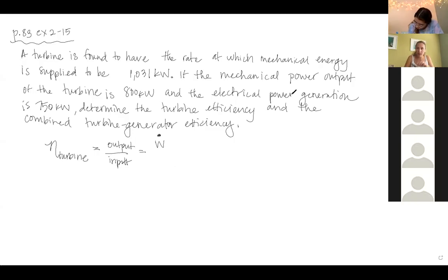So the turbine has that power happening over our moment arm, applying some torque and turning that generator. So there's some shaft work being done, and it's going out, right? It's negative. We're producing work that's going out. But for efficiency, we don't really care that much about positive and negative. We just know that work is coming out of our system to the surroundings.